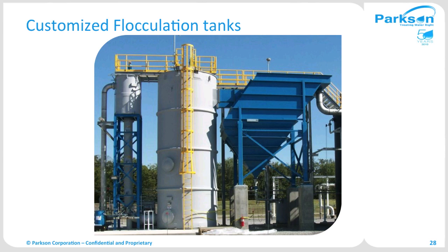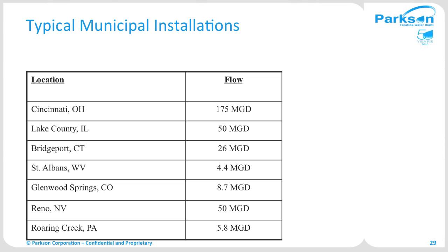As I mentioned before, there will be applications where you would require more flocculation time. So Parkson also supplies customized flocculation tanks with 10 to 20 minutes or even 30 minutes detention time. This example you're looking at is for a surface water application. These are the typical municipal installations. I just wanted to give you a picture of what we have experienced in the past with municipal applications. Our largest is in Cincinnati, Ohio. We have a couple of installations of 50 MGD in Chicago and in Reno, Nevada.